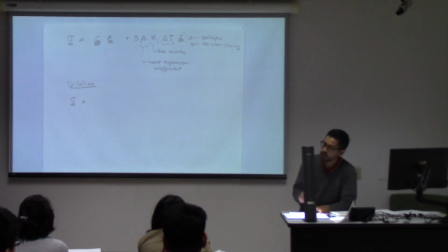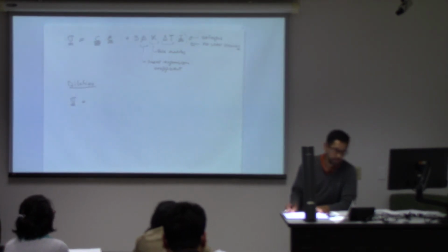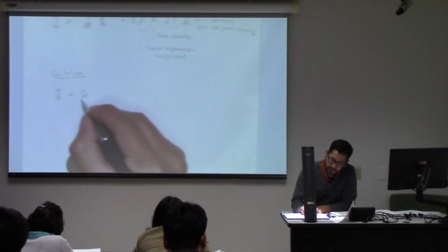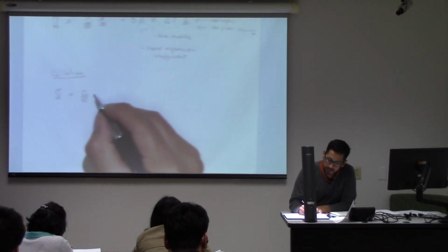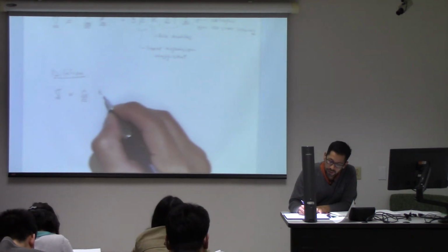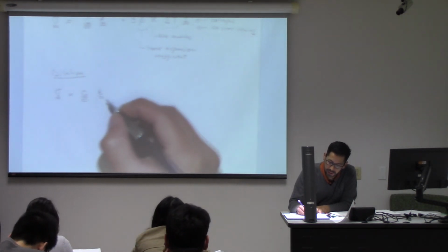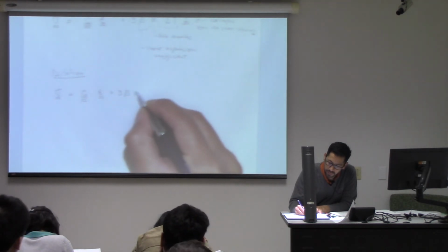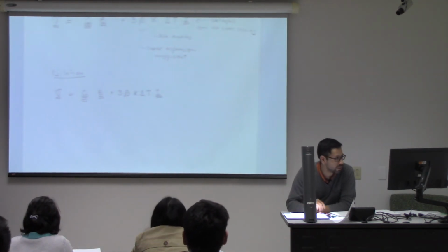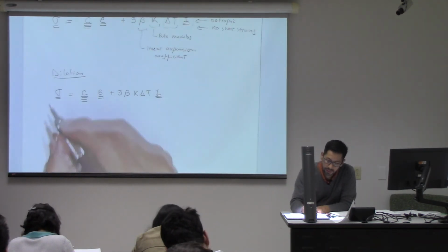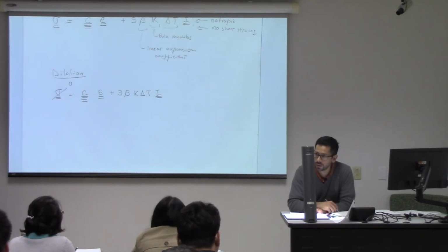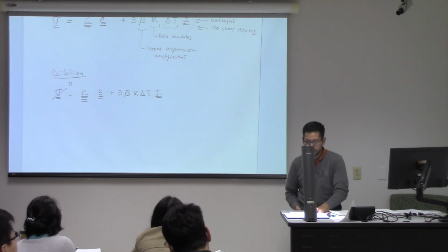So sigma or S is the same. Then what is going to be the stress if I just have a dilation case of an unjacketed rock without any confining pressure, nothing on the sides? Okay, constant, but it probably will be easier if we just say that this is going to be 0, right? There are no stresses on the side. We're just letting this solid expand due to the change of temperature.